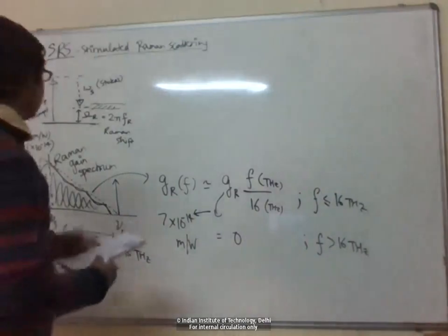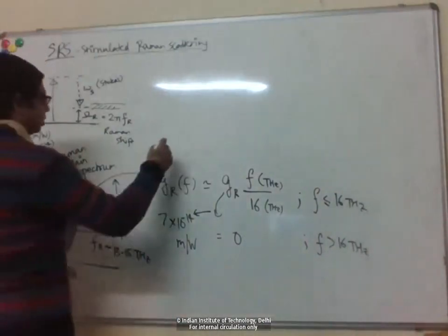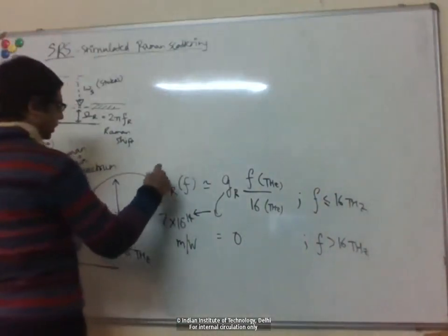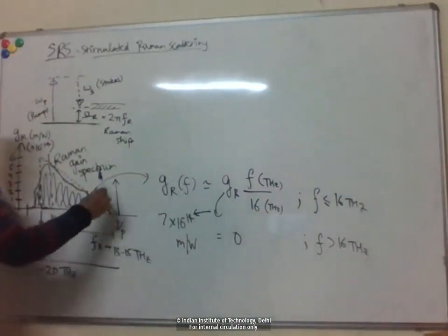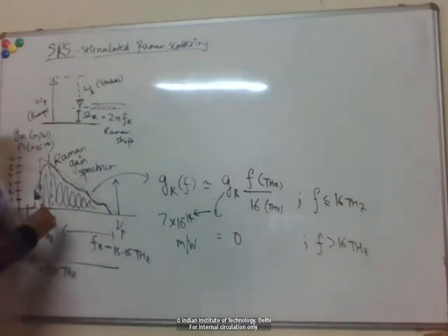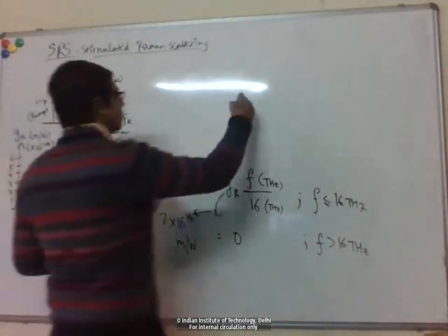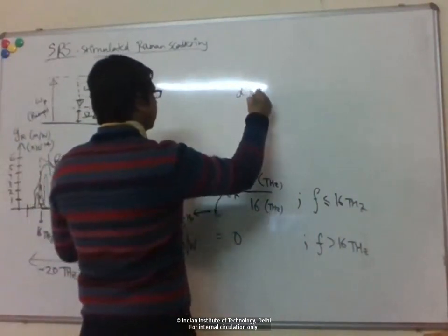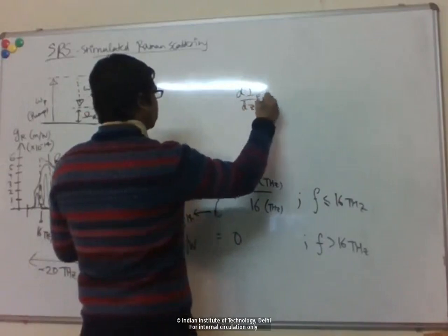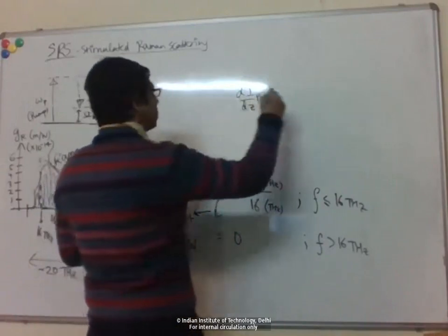Okay, and basically again, what this Raman scattering does is it couples waves traveling in the fiber. So if you have two waves, one at the pump and the other at Stokes, which lies within this gain spectrum, then they couple, right? Just like the Raman scattering, we have now propagation equations for the pump and Stokes.